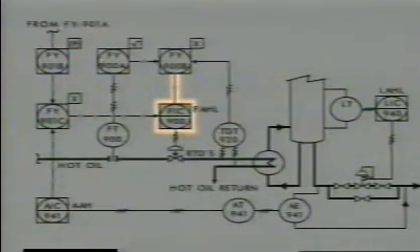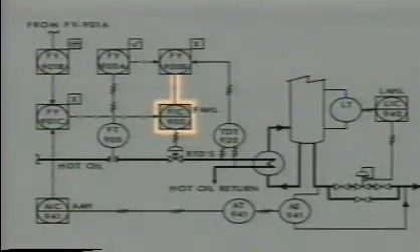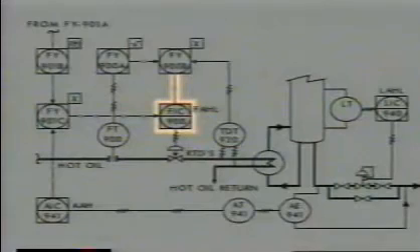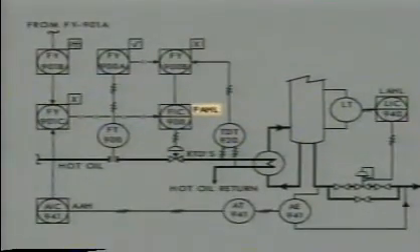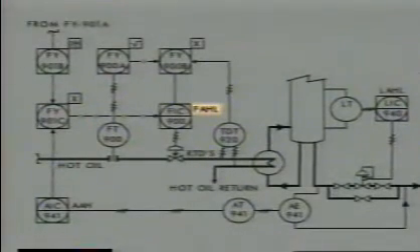This is a flow indicating controller in loop 900. From its symbol, you can see that it is part of a shared display, shared control. The center line indicates there is operator interface at a primary location. The note adjacent to the symbol identifies this as a flow rate alarm that actuates at high and low conditions. That means that the alarm is activated whenever the flow rate of hot oil to the reboiler is outside those limits.